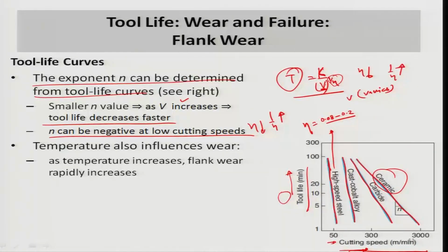Temperature also influences wear, as the temperature increases the flank wear rapidly increases. So far we have seen what the various possibilities are and how you can obtain the n values from plotting the tool life with respect to the cutting speed and determining it from Taylor's equation, V t to the power of n equals C.